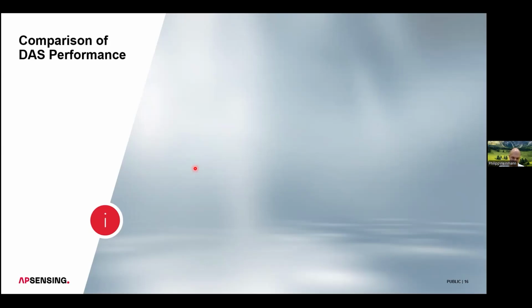Yes. So as long as the attenuation across 20 kilometers is not too high, then you're fine. That's why I was giving this number. Typical single mode fibers offer an attenuation of 0.2 dB per kilometer, some 0.25. So these are the typical values.